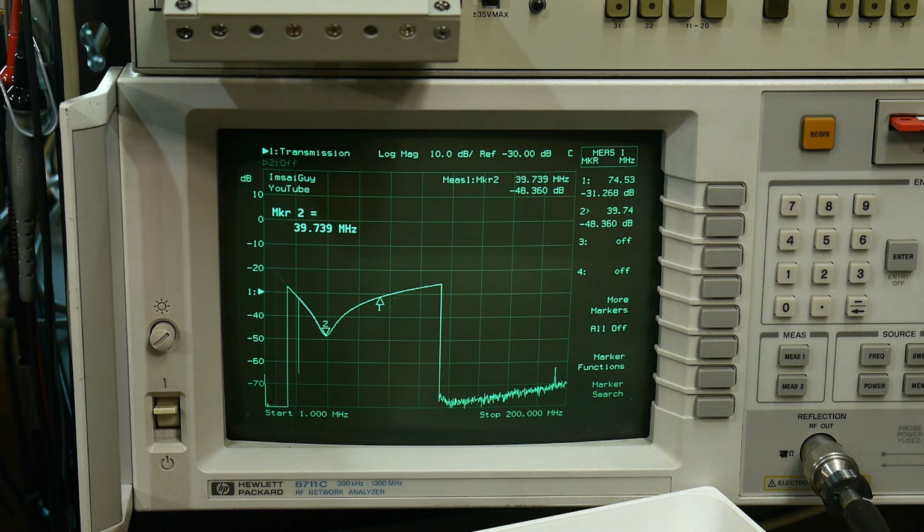All right, I've put in a 0.1 microfarad, and you can see the resonant frequency. It's called self-resonant because it has its own L and its own C. It's all self-contained, so it's self-resonant at a particular frequency. This time we will set another marker. It's resonant at about 8.33 megahertz. That's good. Remember, we wanted something maybe around 10 megahertz, right? Right here at 10 megahertz, it's still doing a really good job. So that's a good one for 10 megahertz. But we lost our 40 megahertz version.